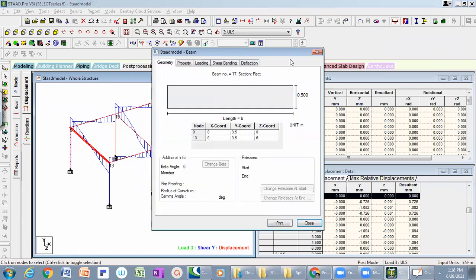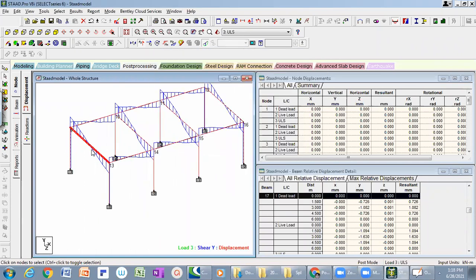You can see, if you double click a beam, for example, I am taking this particular beam. If you want to know the beam number, there is an option. Previously you had numbered the nodes. If you want it for the beams, first of all, if you want to remove this number, press Shift N again.